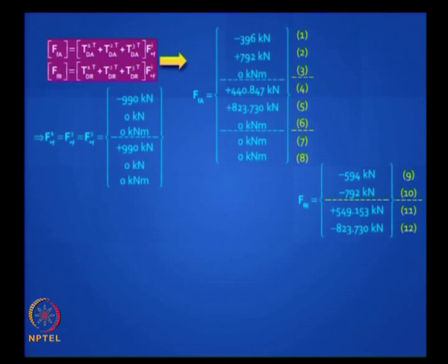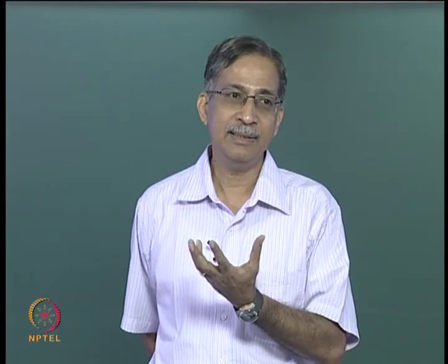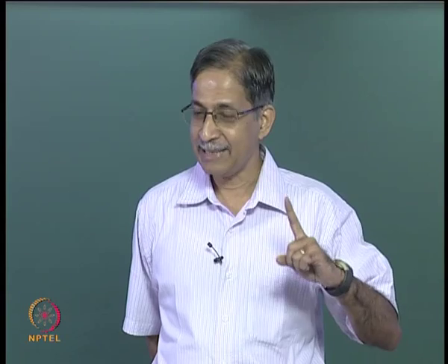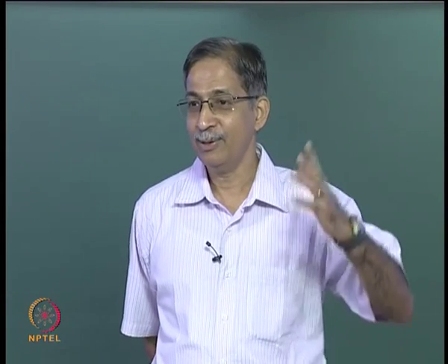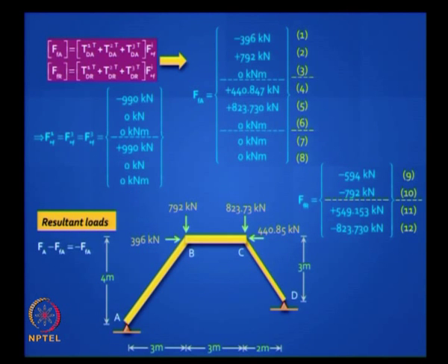And this is beautiful. Only matrix methods does it so efficiently. If you had to do it manually, figuring out what are those equivalent forces is going to be tricky. So this is the power of the contragradient principle, how effortlessly from the actual force in the restrained structure you are getting equivalent joint loads. It's beautiful, very powerful. And so you can find the resultant loads, which is Fa minus FFA. Fa is a null vector because this structure has no direct loads acting on it, and so this is what you get.